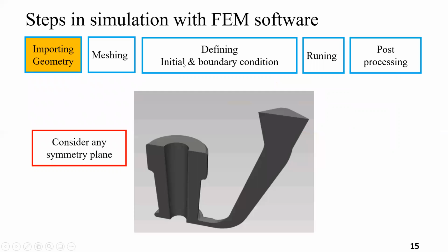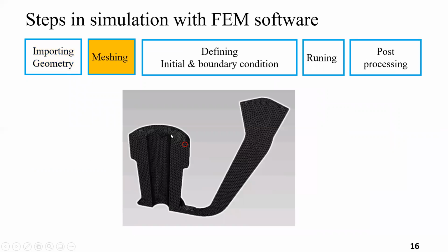So if you convinced, now I want to show you the basic steps that you have to do in any kind of FEM software. You first need to import the geometry, and in that you have to consider any symmetry plane, because symmetry condition can save the time considerably.